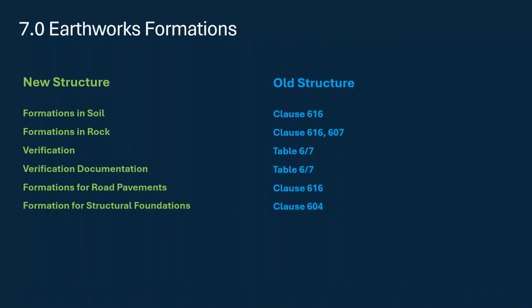Finally, moving on to earthworks formations. Again, a lot more detail on this in terms of actually testing the formation, where you do proof rolling, visual observation, your verification of the formation in terms of tests and documentation, and for specialist requirements you're referred to the road pavements series in places, and likewise the structural series as well. So again, work specific requirements covering all those areas. Again, more emphasis on verification and recording.